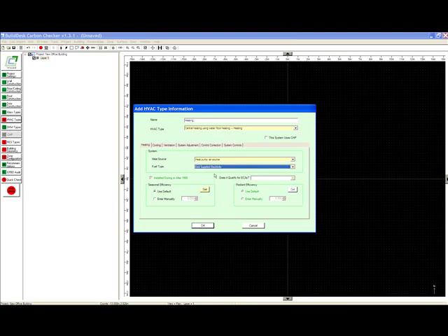For the seasonal efficiency, we could press the Get button to get the default value, but we're going to enter our known value of 3.5, which is fairly standard for this type of heat pump these days. Now, if you had a cooling system, you could go up to the tab up here and enter information about that.